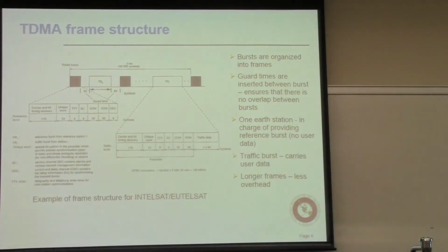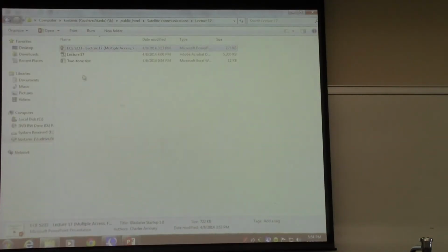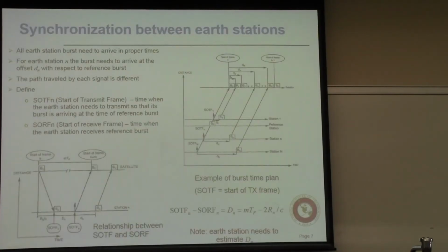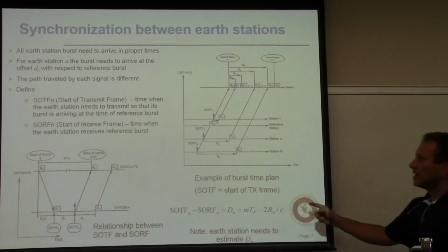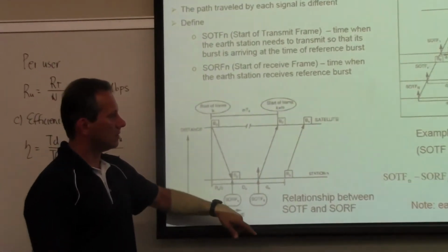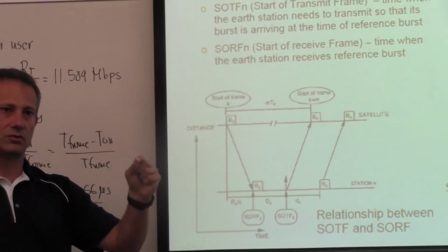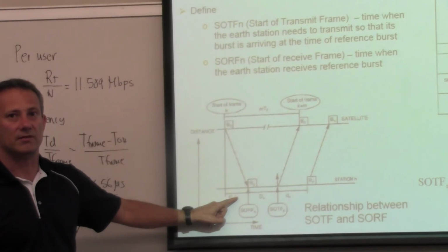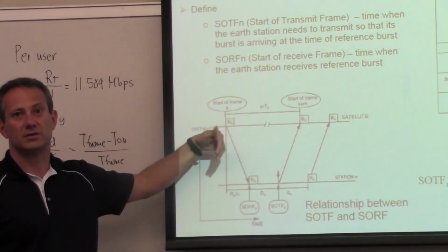When you estimate in GSM or terrestrial systems, you're usually estimating over a single frame, right? Here, if you look at the duration of time over which you're doing estimates, it says MTF. How large is M? Well, what did our example say just a couple of slides ago? It says, let's assume the time frame is 2 milliseconds. So the duration of the time frame is 2 milliseconds. What is the duration of Rn over C? Rn is the distance to the satellite divided by the speed of light. It can be 100-something milliseconds, right? So this n is several, even 100 frames further down the line, right?